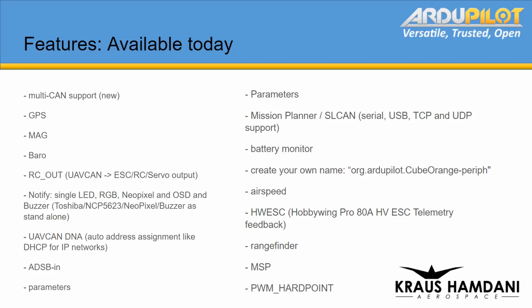With that, this allows you to have multiple CAN ports on your vehicle, and you can run them out to some other target, and that can then turn into 16 GPIOs or whatever out on the end. So it's all controlled over CAN, and all the hardware's kind of done there. You can just put a PIC SoC or whatever on the end.